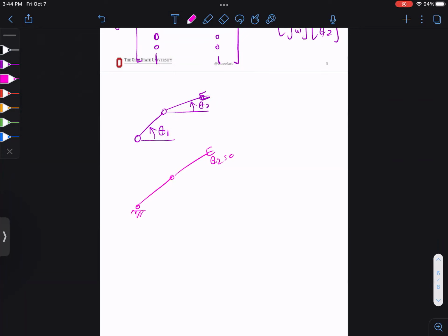Because now that your theta 2 is 0, what happens to your robot? If only theta 1 moves and theta 2 is lost, you converted from a 2R robot to what? 1R. So you took 1 degree of freedom out of it, right? So the definition of singularity is when you remove an ability of the end effector. The end effector might not be able to reach all the configurations, not just the positions that were possible with this robot. Now, what was the other singularity?